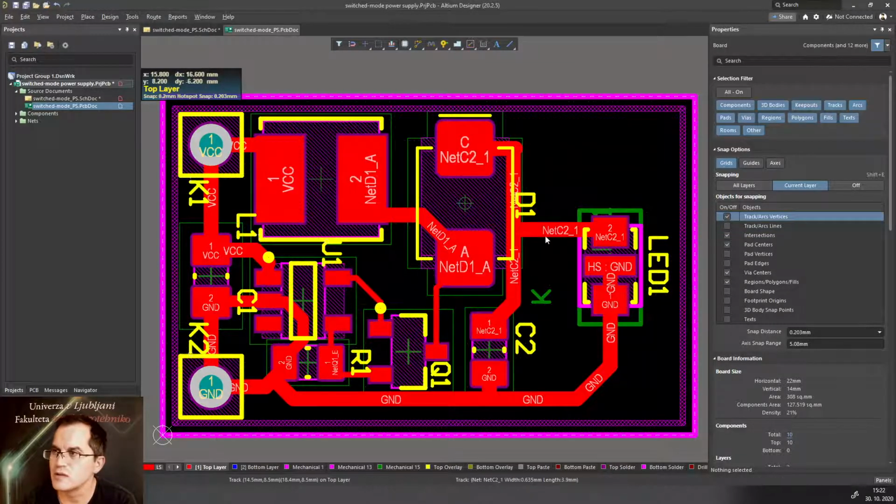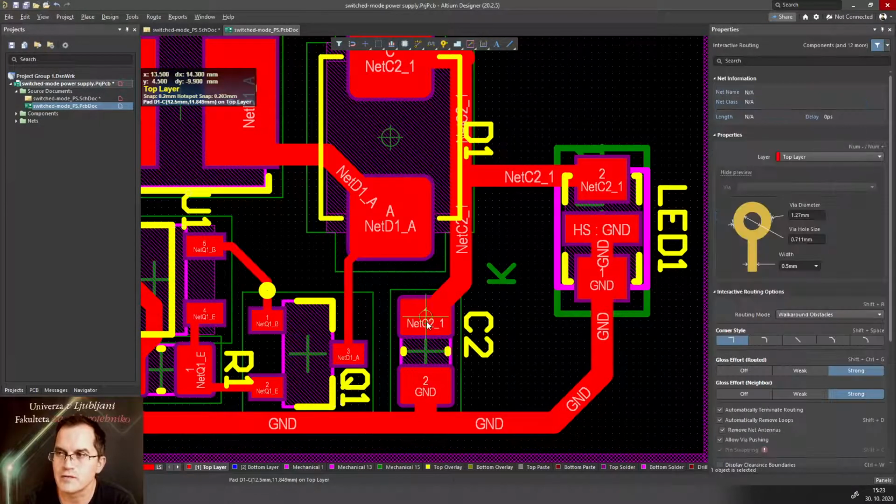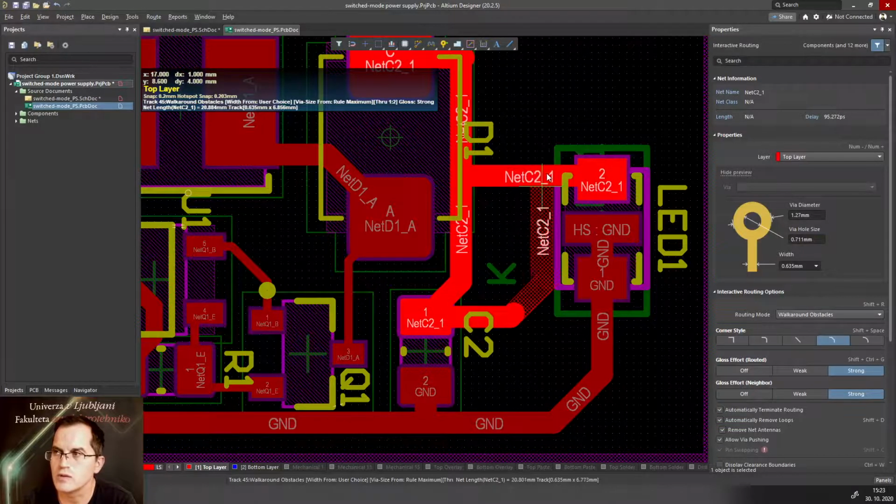Maybe just to remind you, the output on the diode, so this area here, should be as small as possible. Therefore, you should make it smaller by taking the track from this capacitor. But not only that, it should also contain no high frequency currents. How can you do that? Well, take the voltage to the LED diode from the most calm part of the voltage you can find, and this would be apart from the capacitor. So I would do it like that.